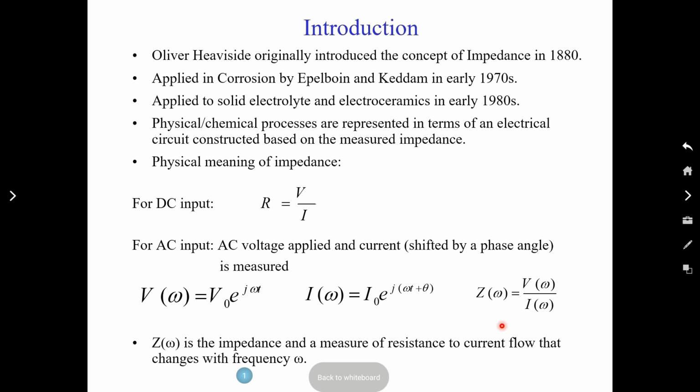So the impedance analyzer, you hook it up to the measurement, and one column will be frequencies: microhertz, tens of hertz, kilohertz, then going to megahertz. It will also split out the real part and the imaginary part and give you that data.